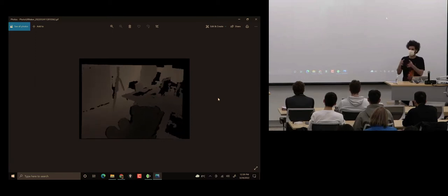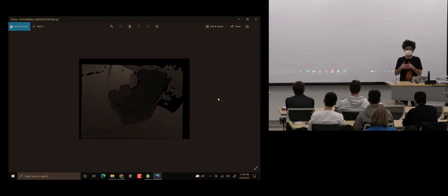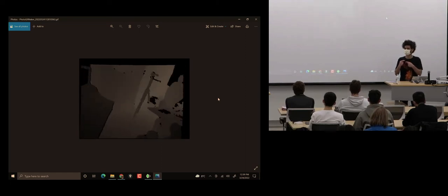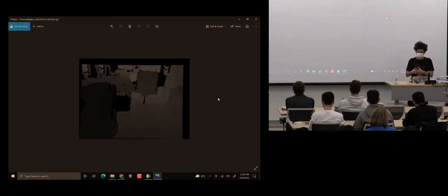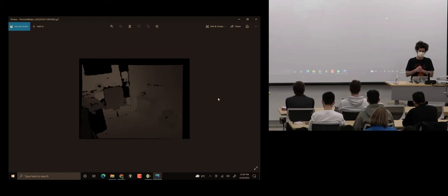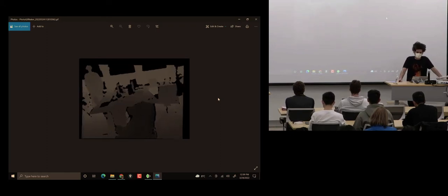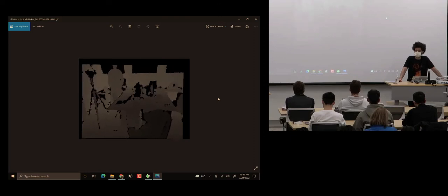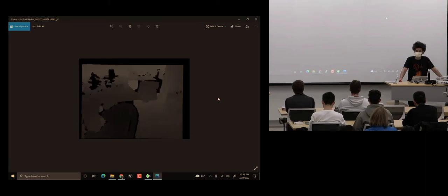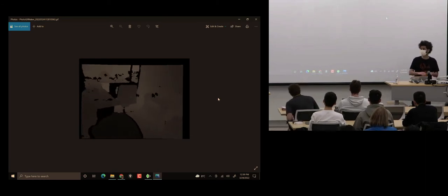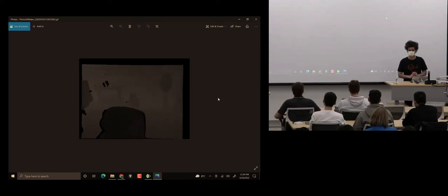Then what we get is registered depth and image data. First of all, they might not be synchronized necessarily. Imagine the frequency of the RGB sensor is different from the depth sensor. Once we register them, then we can get synced depth and RGB images, and potentially with some intrinsic calibration that comes from the factory, you can get point clouds. Okay? And if necessary, we might need to recalibrate the intrinsic parameters of the camera.